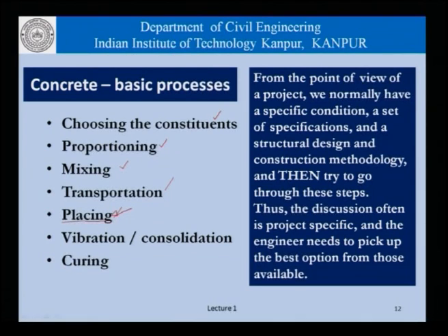After the concrete has been set, it needs to be vibrated or consolidated. What process will be used there? And finally, the concrete needs to be cured. That is, we need to make sure that enough water is available to the cement to ensure complete hydration, or as complete a hydration as is possible.